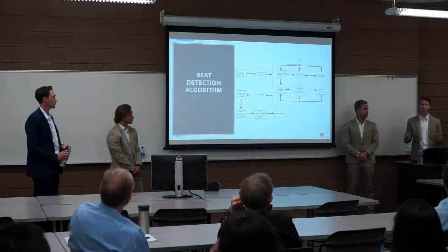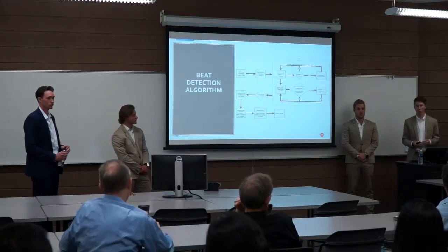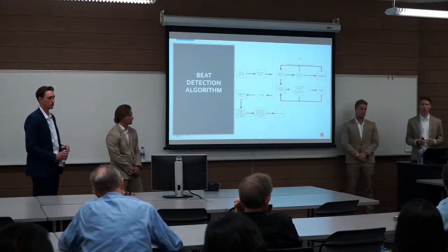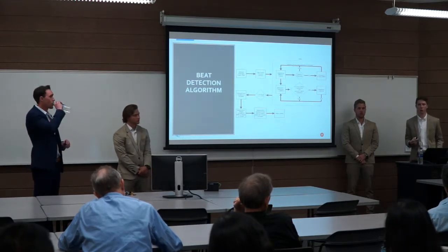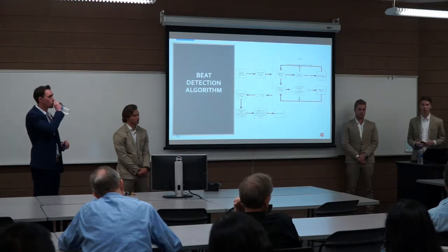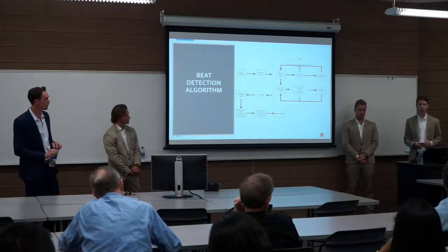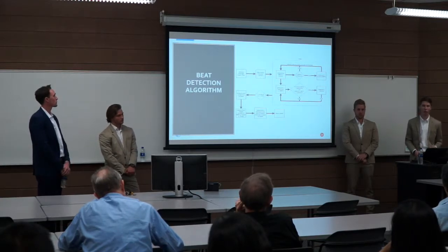Absolutely. We look at each 8-second file as it comes in, and we split it into 20 millisecond chunk files. From there, we iterate across all of those chunk files for that 8-second sample and determine what the maximum level is for that specific file. Normalization, exactly. From there, we set our gate threshold at 6 dB lower than the maximum for that file.